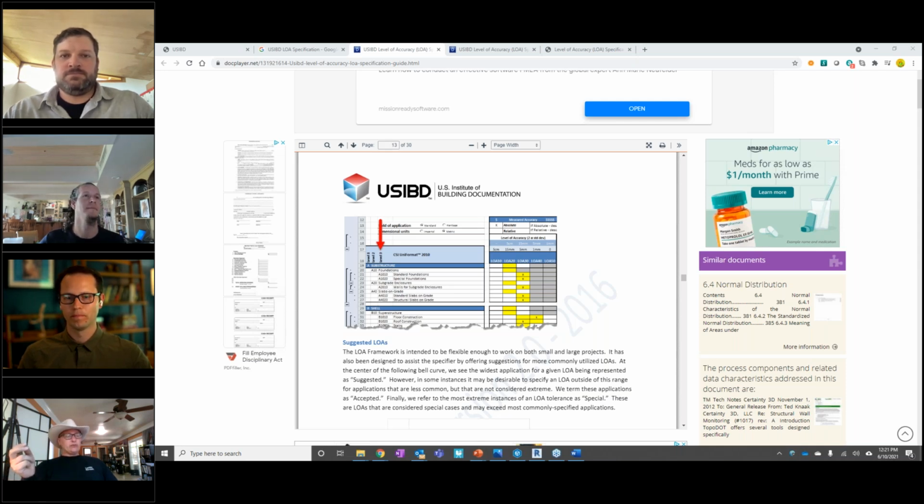And so the honest answer that we probably should be telling our clients is that the LOD is really 200 plus. We're telling you it's a wall. We're telling you it's our best educated guess as to what that wall is made of. But you saying that it's 300 could potentially get us in trouble in a lawsuit.